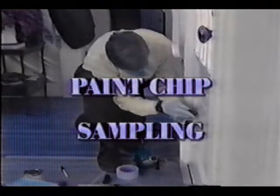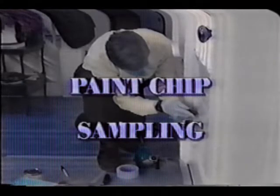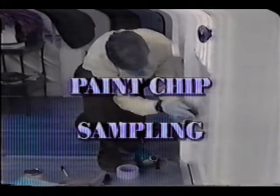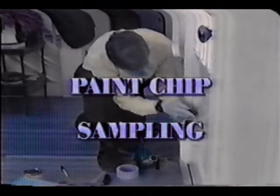Paint chip sampling is one method of testing deteriorated paint. In most cases, risk assessments will result in a need to measure 2 to 10 painted locations. If more samples are necessary, you should suggest that the owner have a complete paint inspection conducted. Paint chip sampling is a destructive method that may release a small amount of lead dust into the dwelling.